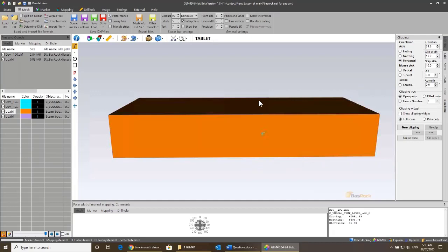Now what's bad about perspective view, if I make a selection within a perspective view environment, because that access into the scene is forever changing in scope, as you go back it gets smaller. There's no one way of making a selection that would be very precise. So the moment you do selections, I'm actually always going to force you, or the software is going to force you to go into something called parallel view. Now you'll see at the top of the ribbon, there's a parallel view checkbox. So let's have a look at the scene, and I'm going to check the checkbox and see how it changes.